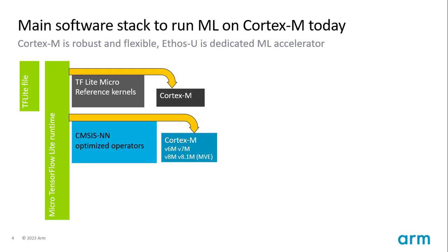You can have a wide range of strides. You can have groups parameters. And all of those attributes are going to run on the Cortex-M. So this means that the Cortex-M is also very flexible for running machine learning workloads. And with CMSIS-NN, you can also leverage the DSP extensions or the vector extensions on the Cortex-M.